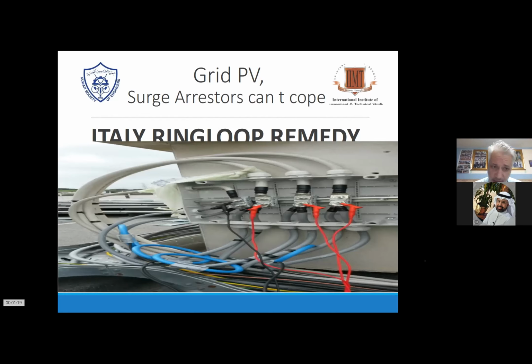And because you have a lot of earthing grounds and a lot of different pillars going into the soil, the modules are always stronger than an earth pit. So that means sometimes the current is hopping. A water pipe, like I said, has some resistance or maybe some isolating parts inside. So the current will jump over to the next earthing, travel along, and then jump back to the water pipe. That could be hundreds of meters, up to the point where the cable goes back to the transformer or wherever this is energized from. That was one of the remedies.